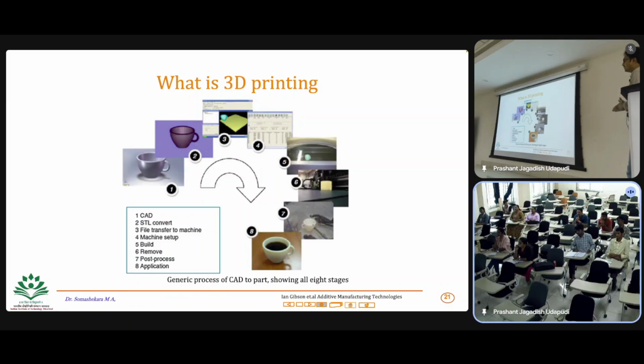But the other part is the machine. You need to have the machine ready before you set it up and print. For example, putting in the right material, and then temperature, or different environment, etc. So you need to keep your machine ready. Similarly, what kind of build plate, and what is the condition of the build plate, and so on. Of course, you can control some of the process parameters, like the temperature you need to maintain inside the chamber, the nozzle temperature, and the bed temperature.